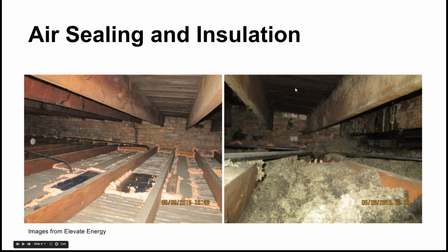This type of insulation is blown cellulose. It's basically fire-resistant recycled newspaper. It has a really high R value, and it's an excellent choice for an attic, especially in the multifamily buildings that I see, that you never have to go into. You just blow this stuff up in there, close the attic, and it prevents all sorts of issues with heat within the building. It keeps heat in during the summer.